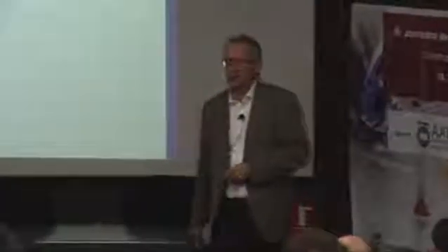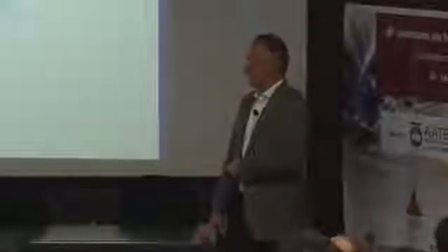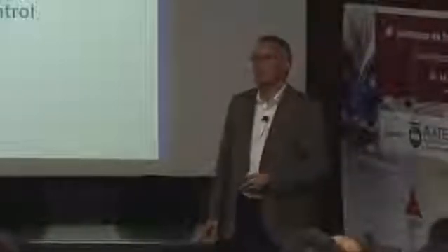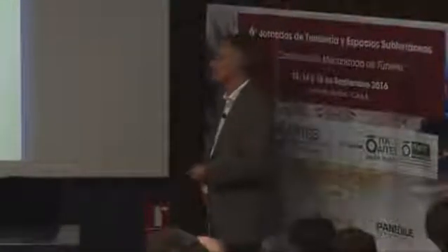Face support failure might require swift action, and that should be done. It's not helping to wait and to discuss. If you have a loss in face support pressure and you have a sinkhole or anything, move on if there's no danger. There are proven methods of gaining face control during intervention. I showed you a couple of solutions. I'm sure there are more than that, but those are proven techniques. With that, thank you.